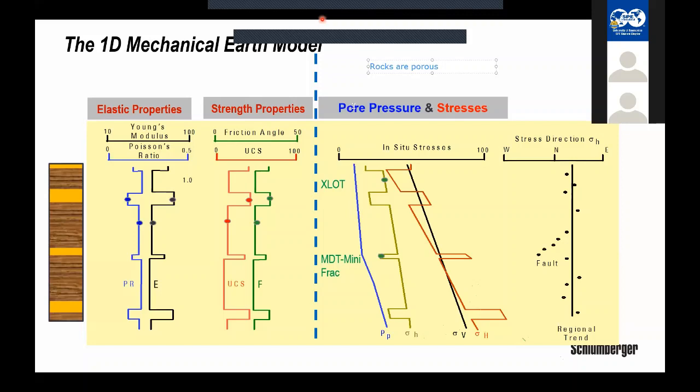Okay, and that's where you see there will be a lot of difference in civil engineering domains as well as in rock mechanics or geomechanics. So in geomechanics, we consider the effect of pore pressure, and in civil engineering, you won't see that for metals, we don't consider any internal pressure in them. So rocks have pores and pores have fluids. Fluids have some pressure, which we call pore pressure.